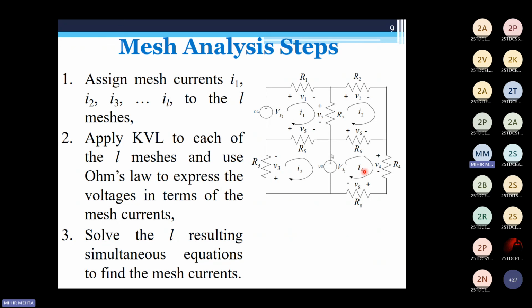So, okay, moving ahead with the diagram. Here you can see that multiple loops can be formed in this particular diagram. But when we talk about mesh, there are only four meshes that can be formed. They're labeled as I1, I2, I3, and I4. In this diagram they have been labeled in this fashion, although it is the choice of the person solving the mesh to number it in any fashion. They can give this as I1, this as I2, this as I3, and this as I4. So it is absolutely the choice of the person who solves this.